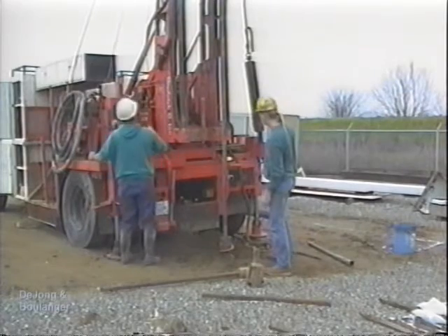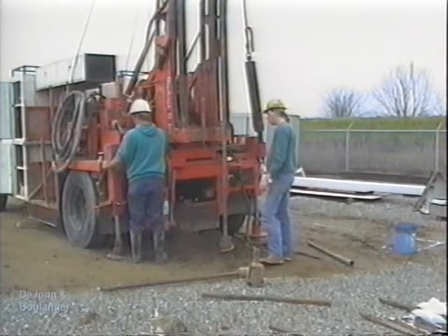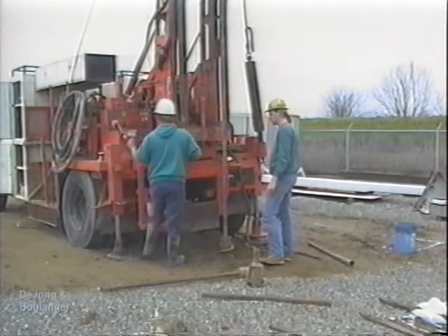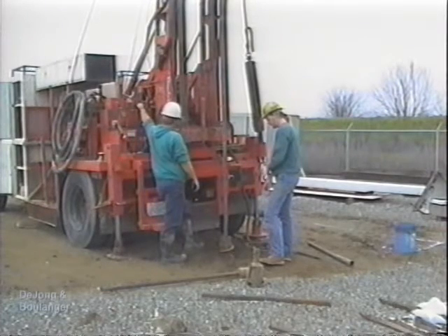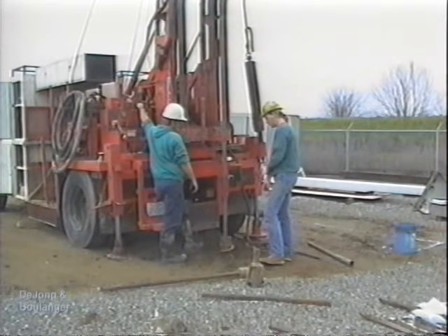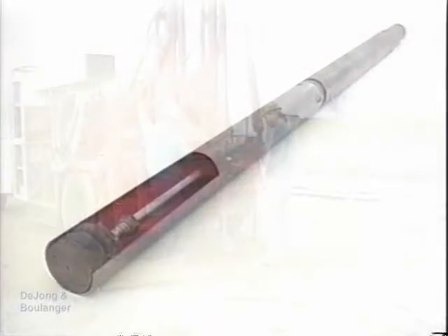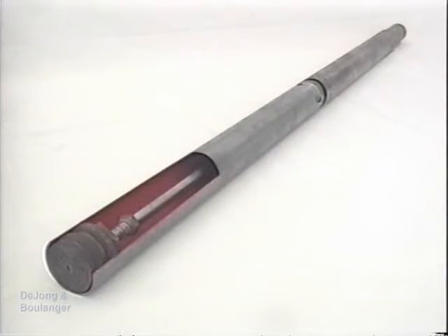These conditions can be greatly improved by using a piston to close the lower end of the tube until the sampler has been firmly positioned against the undisturbed soils at the bottom of the borehole. The piston is then held at this elevation, in contact with the soil, while the tube is advanced around the piston and into the soil.